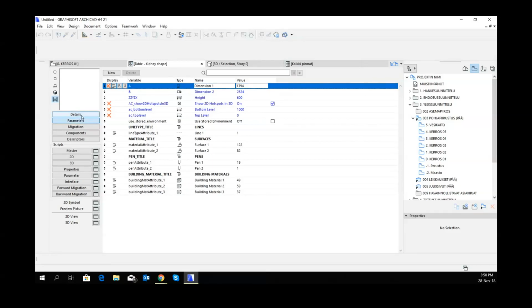So this is all the technical side now, so at this stage I won't worry too much about this. But once you get comfortable with making objects, you can start setting parameters. Like, say it's an object that comes in 2 sizes, you can say that dimension A can only be 600 or 1200, or it could be between 600 and 1200.